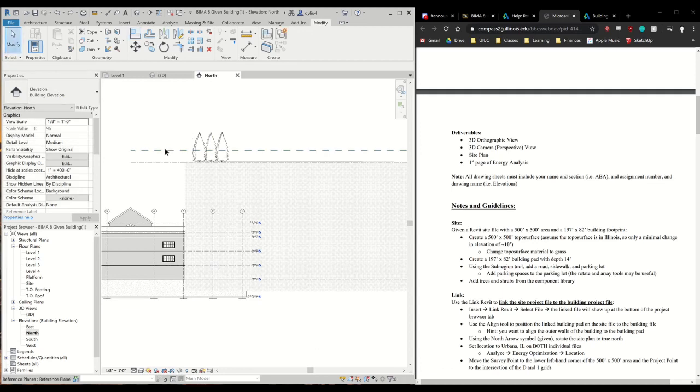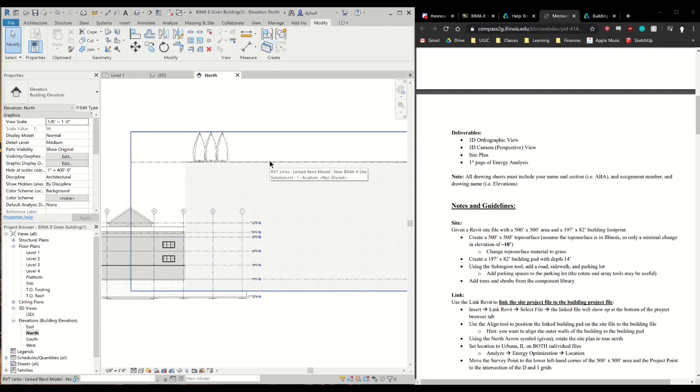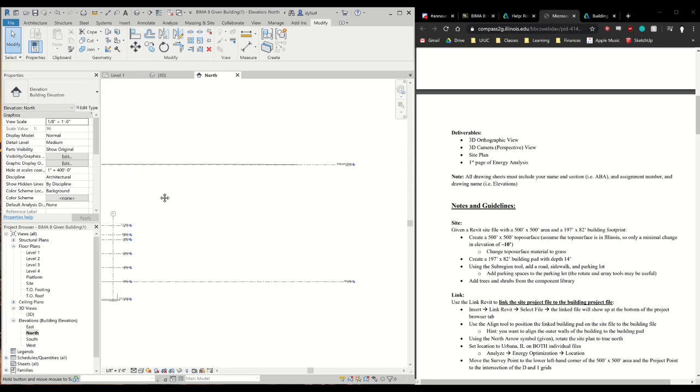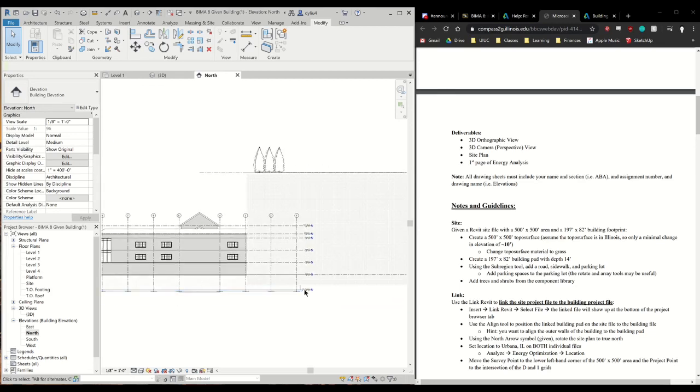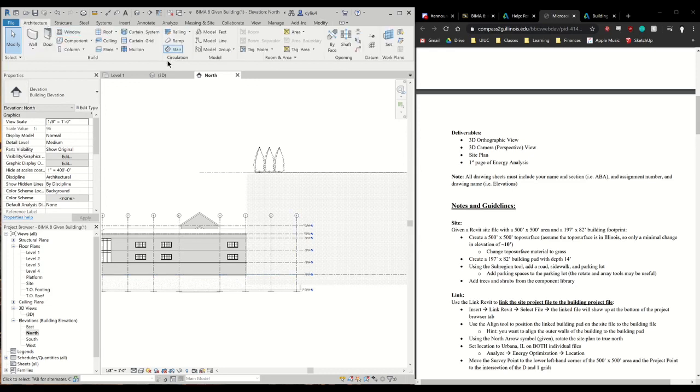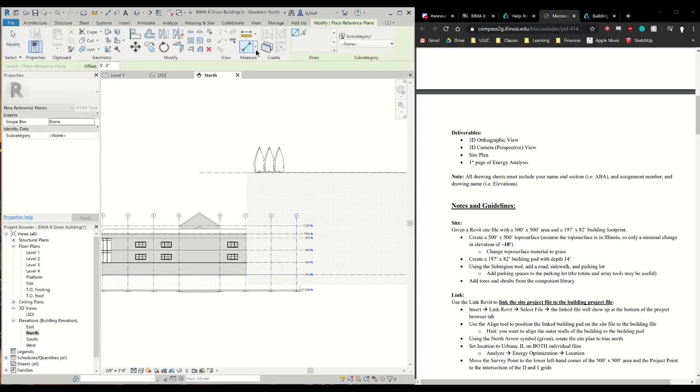We're going to actually create the reference plane below my existing level. Because the problem that happened there was actually I put the reference plane on the non-host level, the linked level. I want to put my reference plane based off of this. So I will instead create a reference plane, RP, and then I can define a 10-foot offset from level 1 downward.